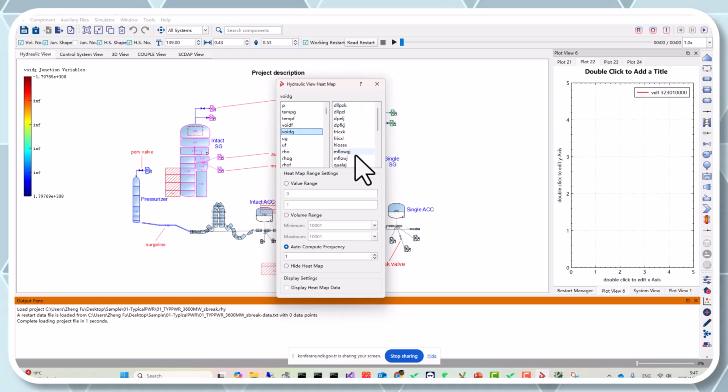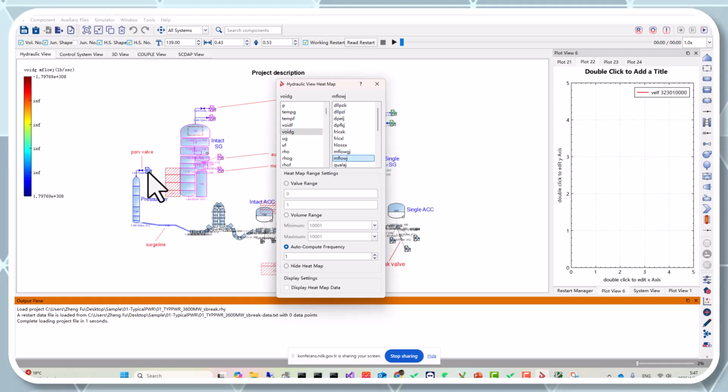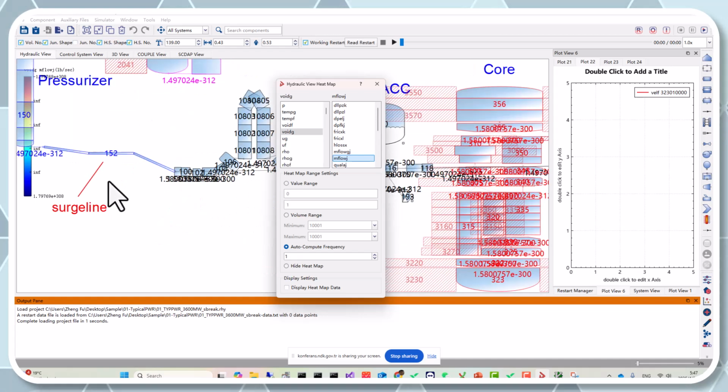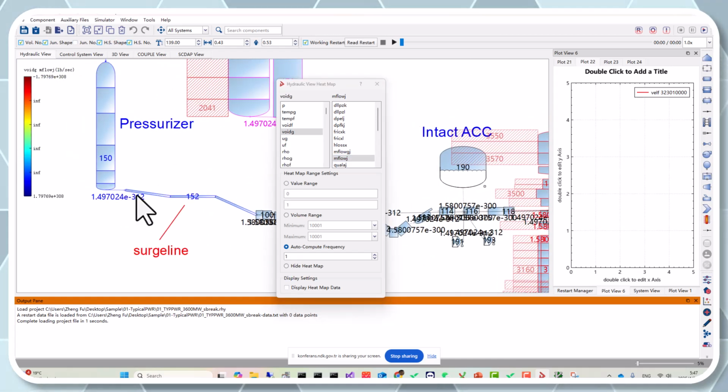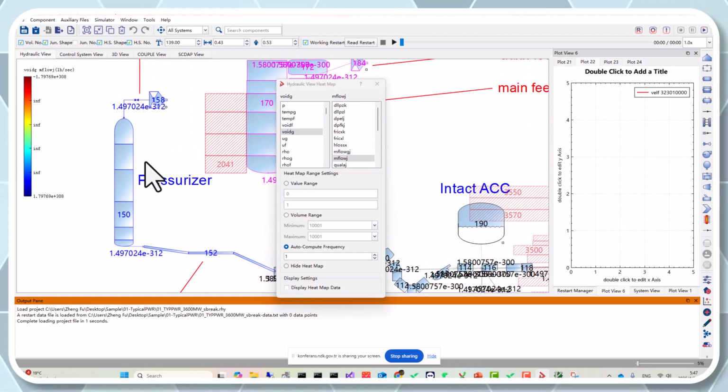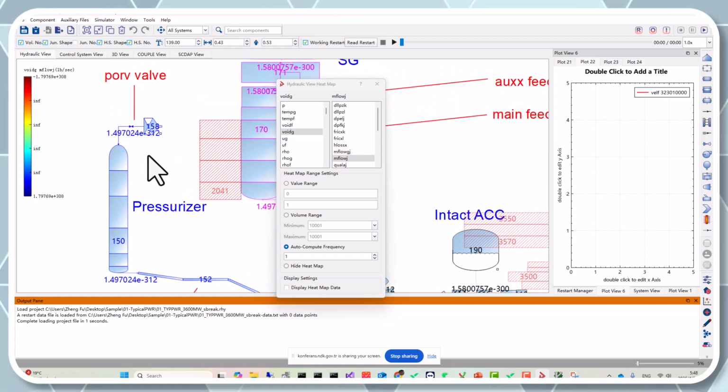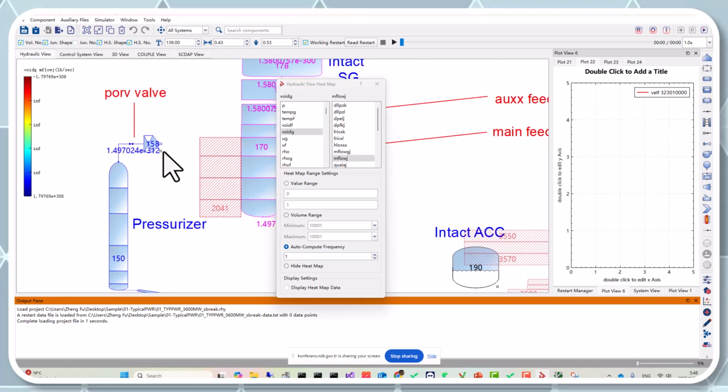And on the right side of this column, it's not heat map, but it's showing the junction data. For example, I can double click on mass flow, and then that's going to show you, if you zoom in, you can see there are numbers. This is actually 0. It's the initial condition, but it's minus e to the minus 300 something. Anyway, so there are two things you show on the heat map. One is the Y fraction heat map to a bar, and then the mass flow rate appears on each junction.